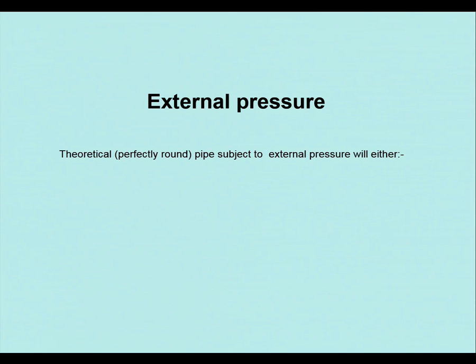So we've locked in the air, and that is atmospheric pressure, except for the weight of air down the pipe to the seabed. So it's effectively nothing. But when we lay that on the seabed, we've got the external water pressure plus the atmospheric pressure on the inside. So that's going to give me my maximum compressive hoop stress.